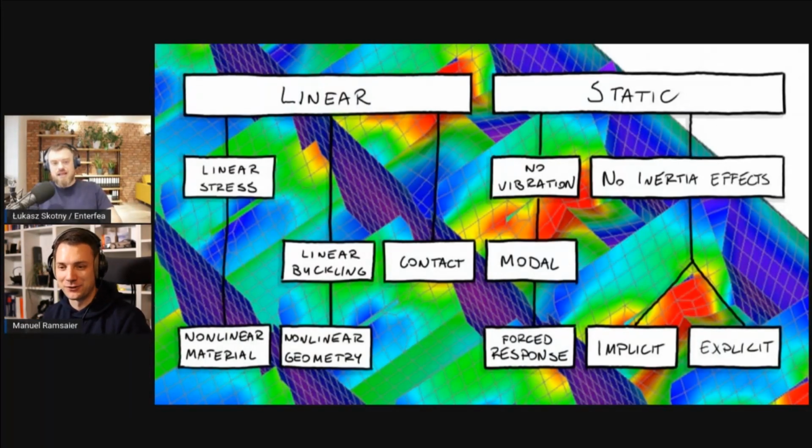But yeah, for sure. The beauty of it is that when you know the stress-strain relation of your material, you can compare how much strain you can accept. It's a simple relation, an actual limit. And what's even better, the codes and standards for design will often tell you we don't allow plastic strains higher than this much for this grade of material.